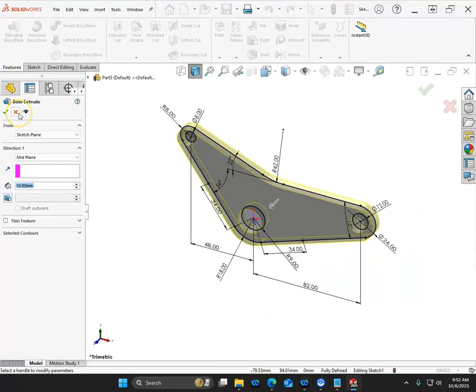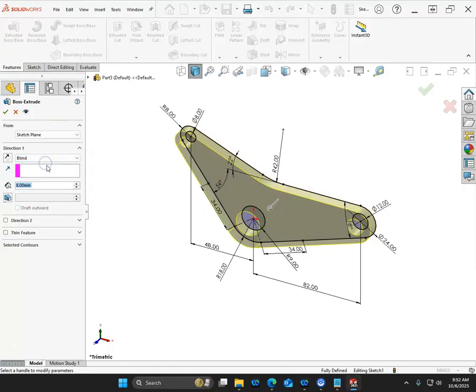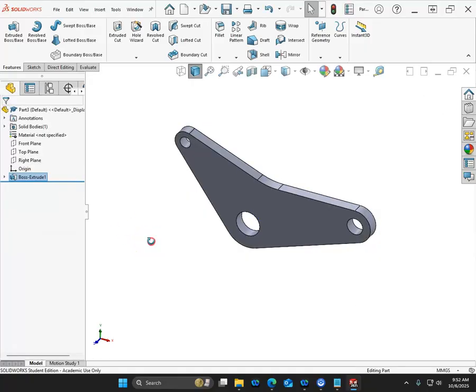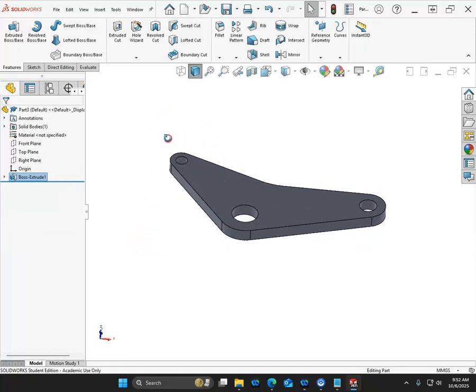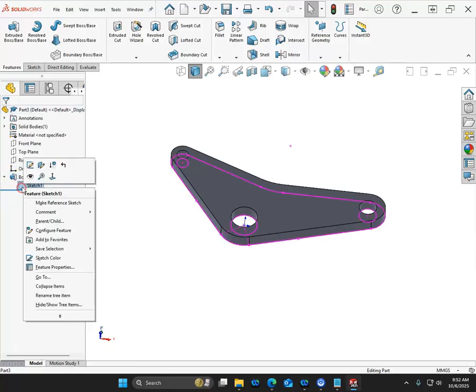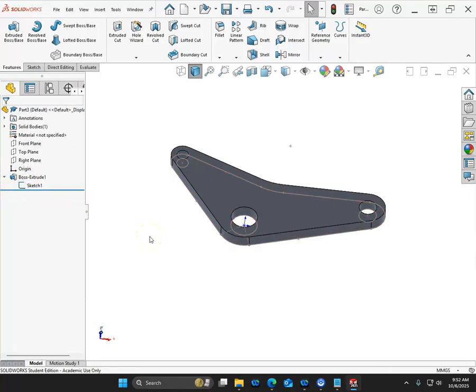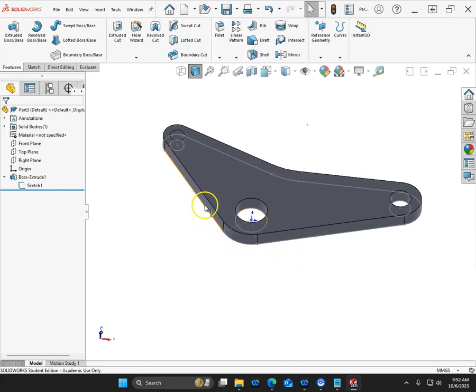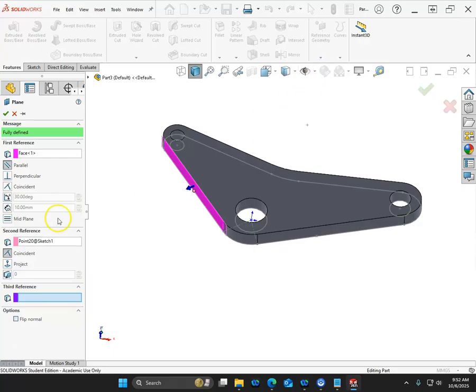All right, so we're going to extrude, and the thickness is 8, and we are not doing mid-plane. We're going to stay in blind end condition. Now the other thing was that was at the bottom. Does that affect anything? So when we show this, I don't think that it's going to matter whether it's up here or down there. So let's go ahead and see what we get with the first. So if I pre-select, it will automatically populate those.